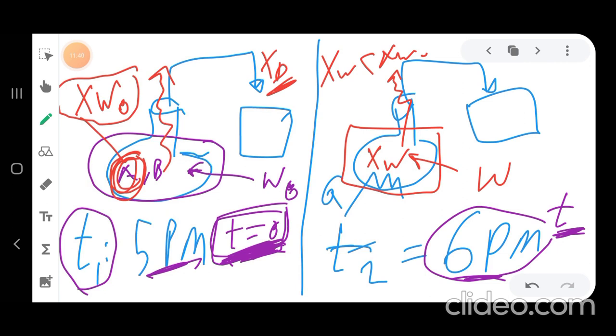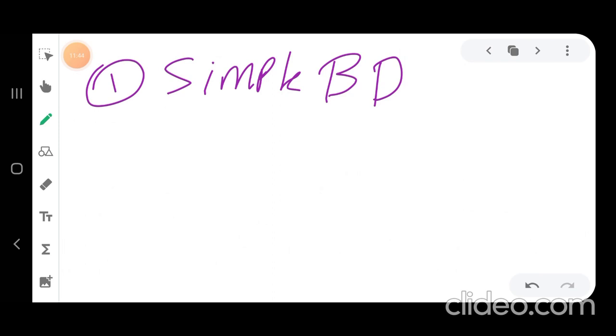Yeah, that's the Rayleigh equation. So now let's start with the simple batch distillation. In simple batch distillation, we don't have reflux, we don't have stages, we don't have this complexity. That's why we can say that the distillate composition is nothing but the composition in the vapor phase, because we have only a single stage.